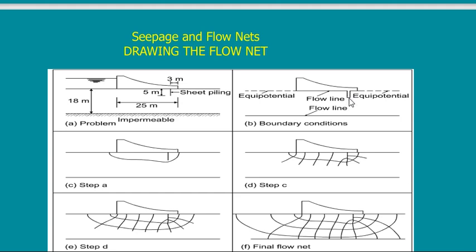Usually we put a shear key, or sometimes it is called a hydraulic key, because it prevents the structure from sliding, and at the same time it hinders water from passing. Do you know why, if I put something like this, water will be affected?